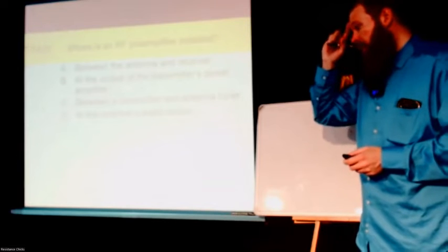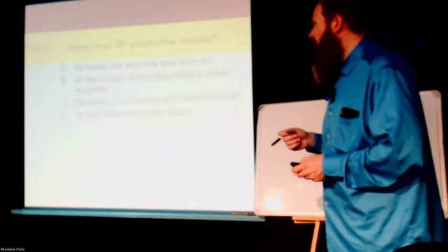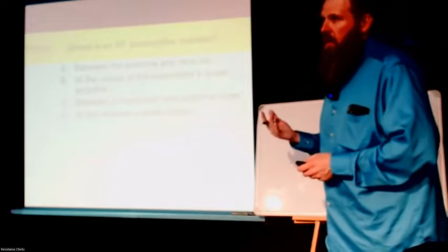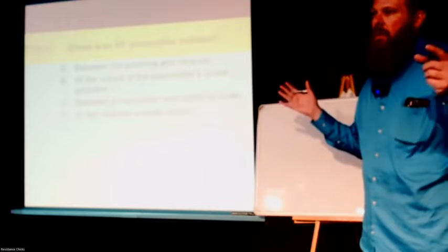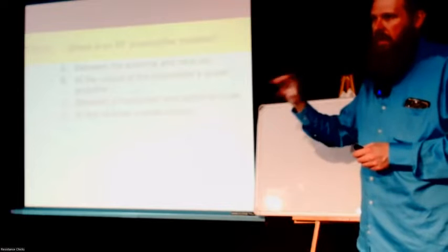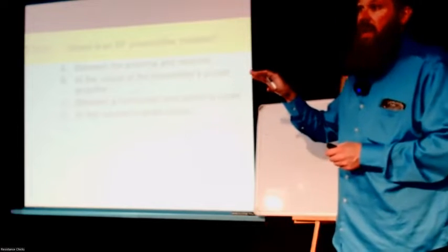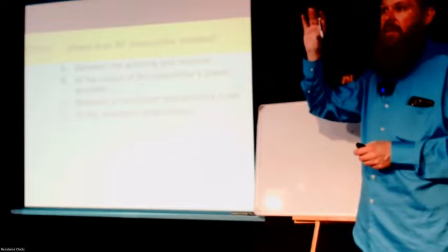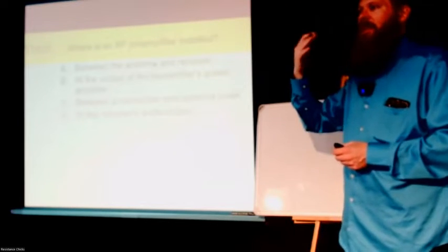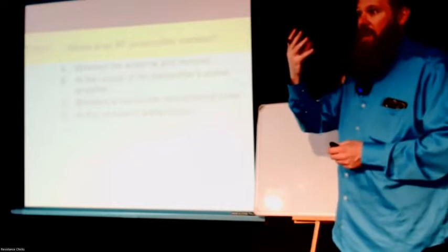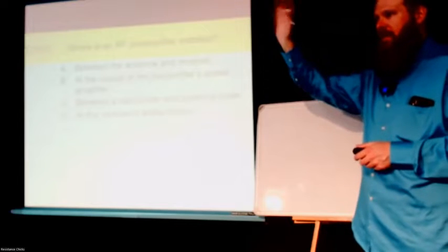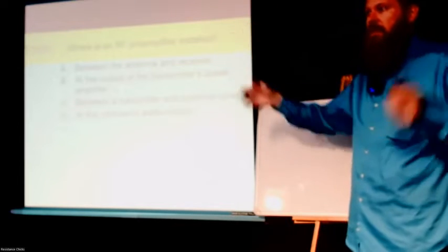Well, on an AM station, they use systems called compression, where they try to keep the volume that's fed into the transceiver at a steady rate and always high, because the amount of power it puts out varies based on the amplitude being fed into it, the volume of your voice, and they want that to be as strong as possible so they can reach the maximum area.